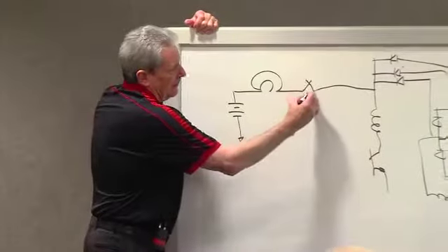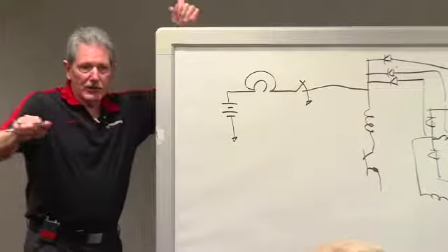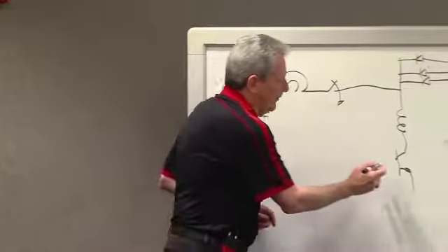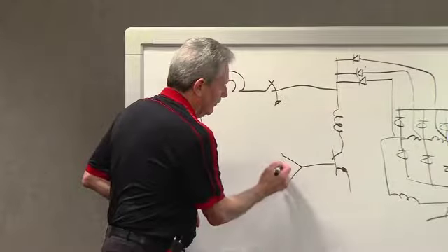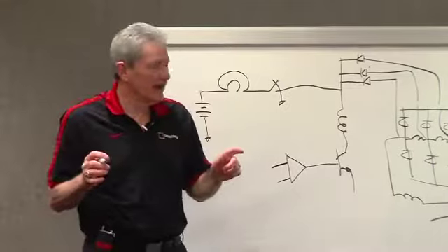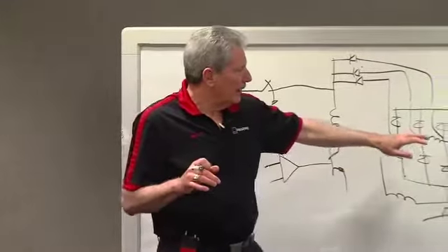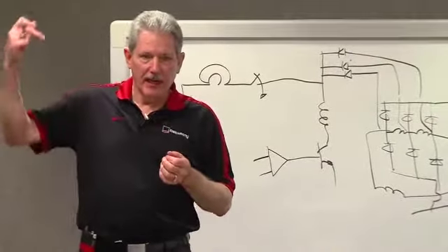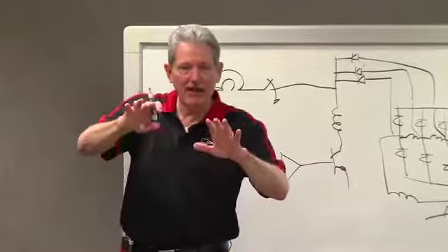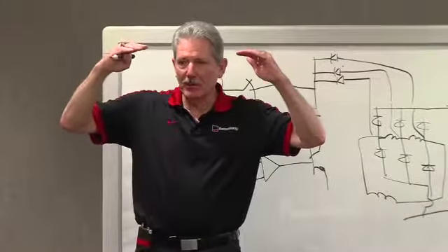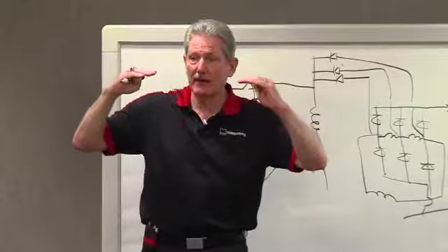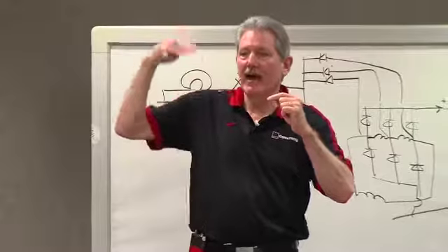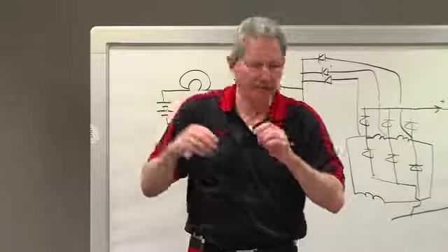Okay, so I turn the key on. As soon as the key is turned on, remember I'm below set point. Oh, one other detail that I didn't tell you, but it's important here. The charge voltage of a battery is 14.8 volts. I need to push 14.8. But if I take the voltage off, the open circuit voltage of the battery is 12.8. So I have to overcome 2 volts in order to get any current into the battery.